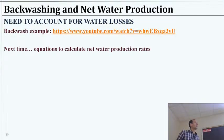What you see in those scenarios is that now that the particles have met each other inside the pores of the grains, you'll have had more flocculation type of stuff happening, and you just have such a high concentration of particles that from there it becomes pretty easy to do sedimentation again. But really that would be in the wastewater treatment. You might have a small wastewater treatment step to deal with this type of waste coming from the drinking water system, but a lot of times they would send it straight to an actual wastewater treatment plant.